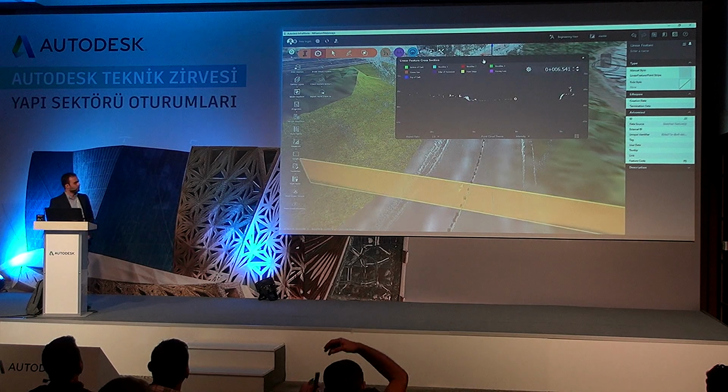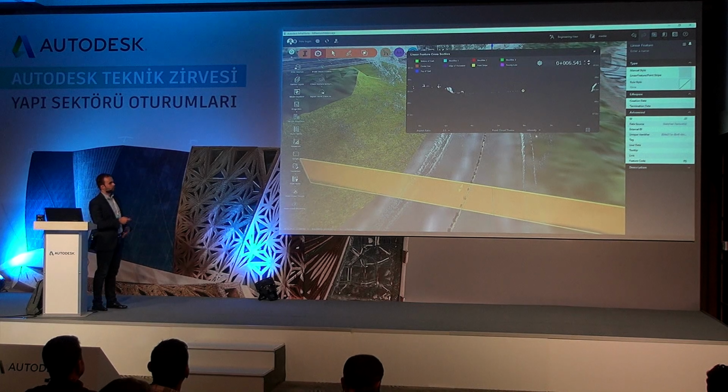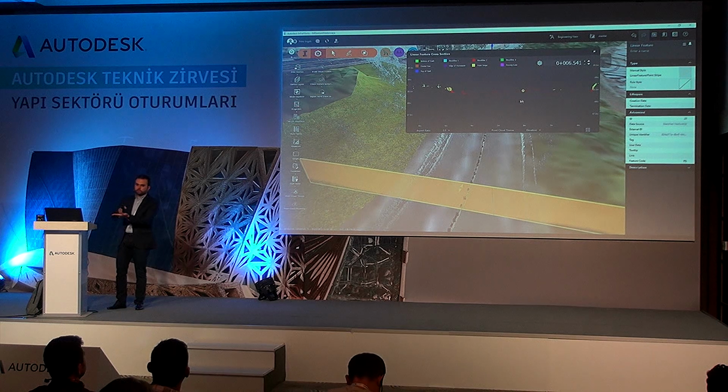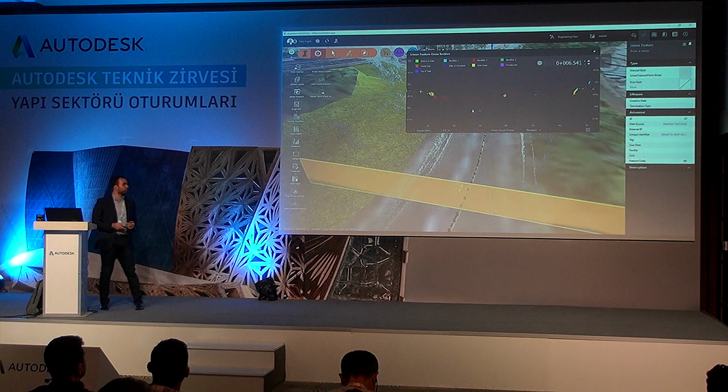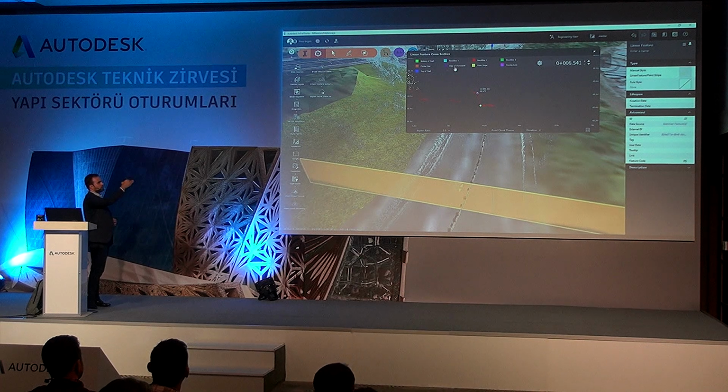Another thing, because sometimes if we're taking the edge of curb and it's not very accurate, right? Sometimes at the edge of curb you have dust or sand or even some plants growing. We have a tool that is the cross-section viewer inside of InfraWorks. So if we don't want to do it in plan, we can do it in cross-section. We take those points, we move to another cross-section, then we go from one cross-section to the other, to the other, to the other.